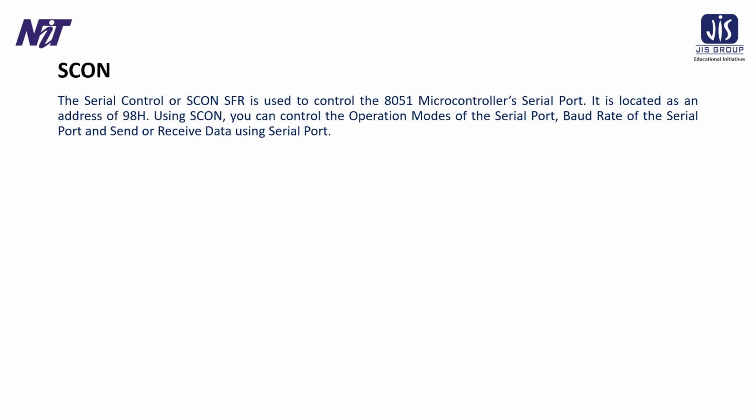Now SCON, the serial control register. The serial controller SCON is an SFR used to control the 8051 microcontroller serial port. It is located at address 90H. Using SCON, you can control the operation mode of the serial port, the baud rate, and send and receive data using the serial port.